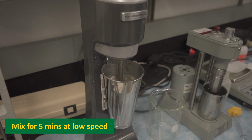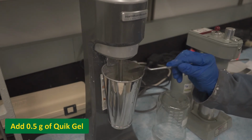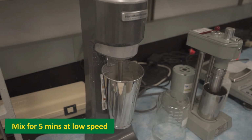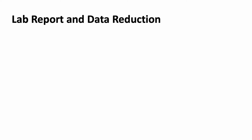Mix again for 5 minutes at low speed. Add 0.5 pounds per barrel, or grams, of quick gel, and mix again for 5 minutes at low speed. Now measure the same properties by conducting the tests done earlier in this video with the previous mud sample, except using the newly created lime mud sample. With that, the experimental procedure is completed, and the lab report and data reduction is next.